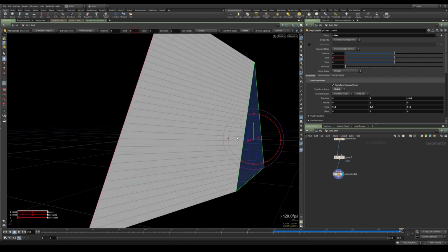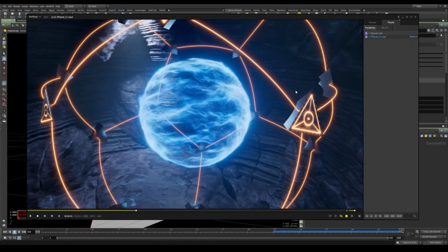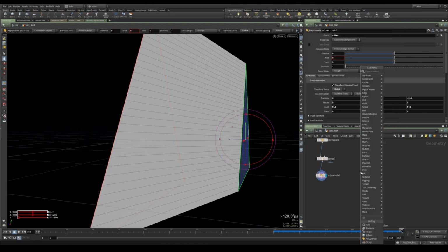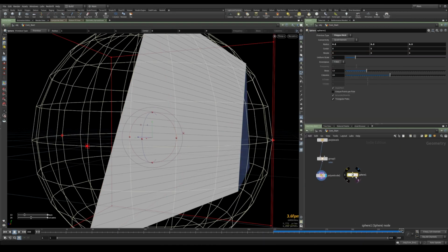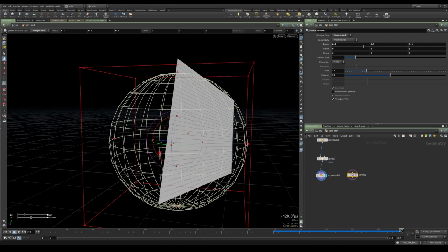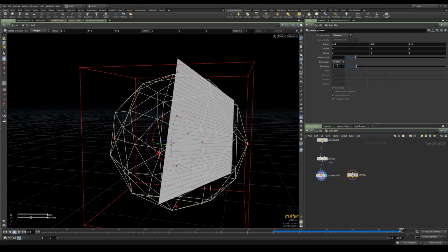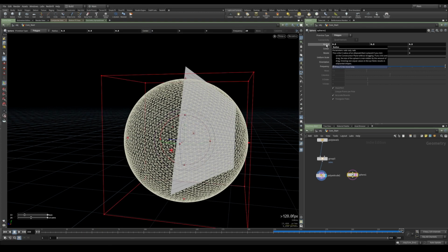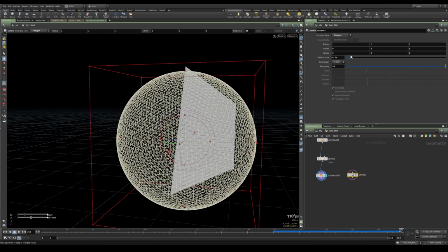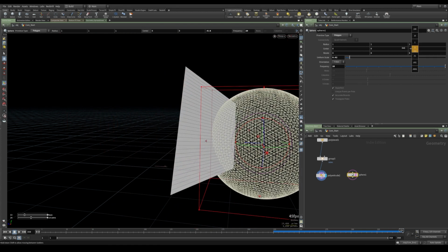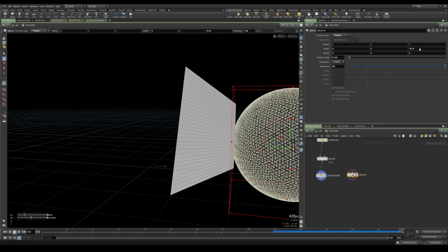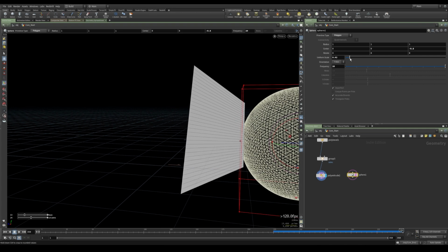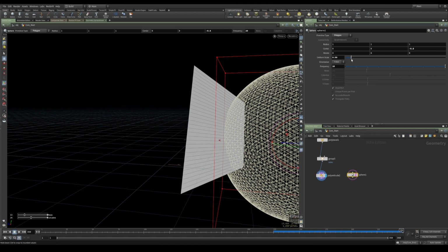The problem is right now we have a straight shape. If we look at the final video, we have like a hollow sphere shape inside the core. So let's create a sphere and put the template flag. We want this to be a polygon type with 20 as frequency. Reset the default radius to 1, and let's scale it down and move it on the z-axis. So let's say 0.8. And I want a size of, let's say, 0.58.